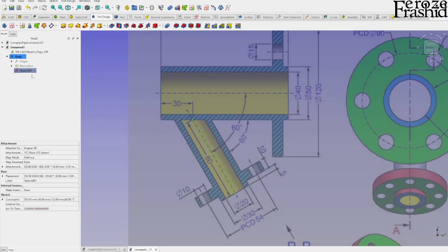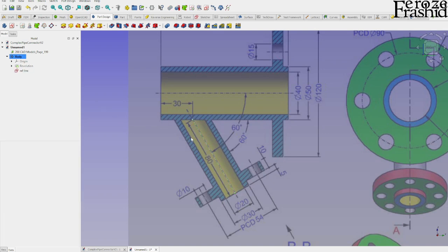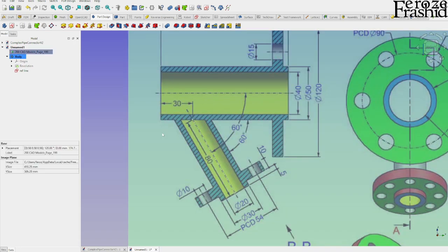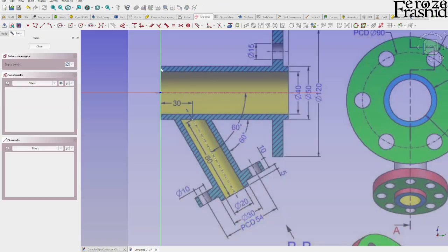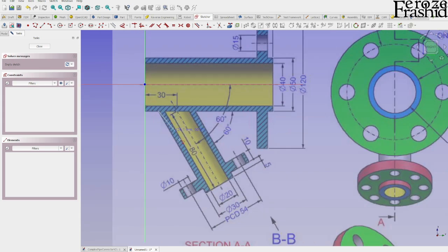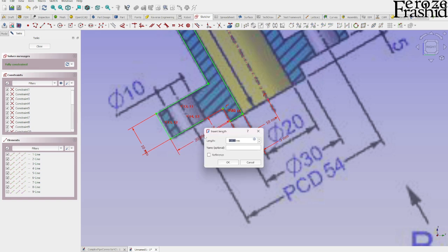That's the end of that sketch. It says reference line, and I want to keep it separate because I want to use it to revolve my sketch. From there, let's draw the actual sketch. On the YZ plane again, and this time quickly, let me take a minute to draw this sketch. 20.